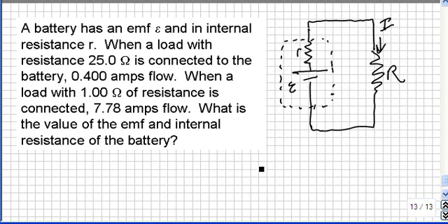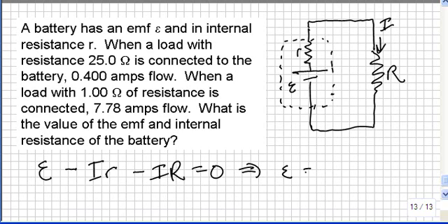If I go up through the EMF, that acts as a boost to the potential. So I go up by a voltage equal to the value of the EMF. I then go through a resistor, a current goes through a resistor. That's going to result in a voltage change a la Ohm's law, and so the voltage is going to drop by minus Ir. As I continue around, I go through the big resistor R and get another voltage drop, I times big R. And then I've come back to where I started. So I know that around any closed loop, the potential change has to be 0. So it implies that the EMF is equal to the current times quantity R plus little r.